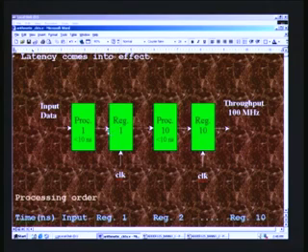It travels in the same fashion that water flows over the pipeline, so after several clock cycles you get the output here. That delay is what in the pipelining process we refer to as latency. To convey it through 10 registers you need 10 clock pulses.